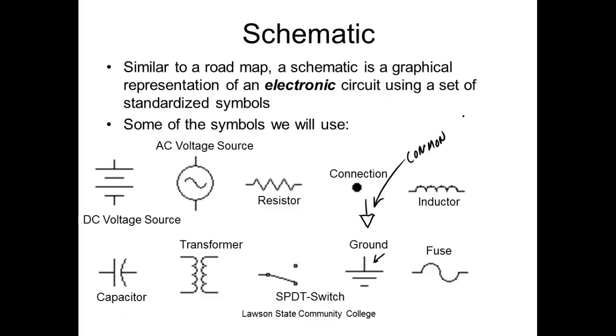Yeah. So your car does not have a ground. Your car has a common, but everybody calls it what? Yeah, everybody calls it ground. I mean, I don't hear chassis ground most often. They say your ground wire's loose or something like that. And you need to understand the difference. So your house has a neutral that is referenced to ground. They don't call that common, they call it a neutral.